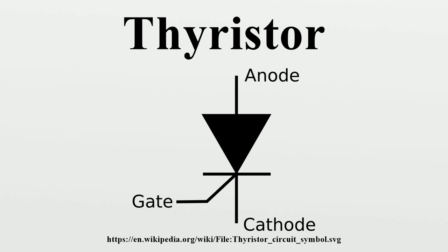The SCRs, unlike TRIACs, are sure to turn off. The price to be paid for this arrangement, however, is the added complexity of 2 separate, but essentially identical gating circuits. Although thyristors are heavily used in megawatt-scale rectification of AC to DC, in low and medium power applications they have virtually been replaced by other devices with superior switching characteristics like power MOSFETs, or IGBTs.